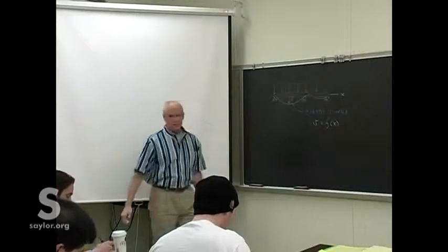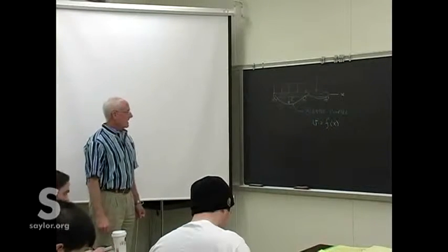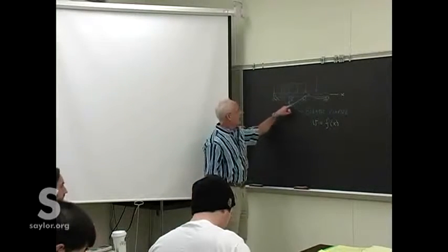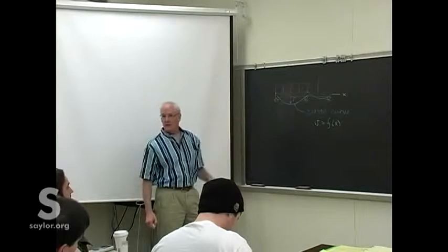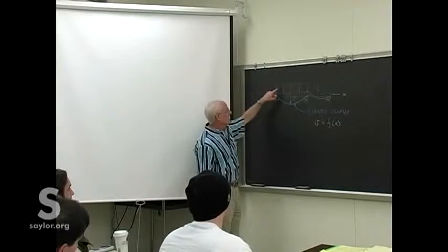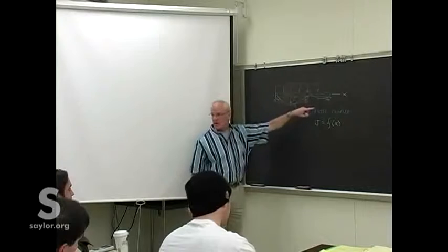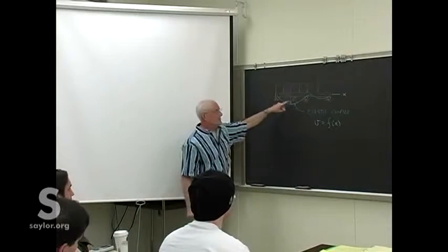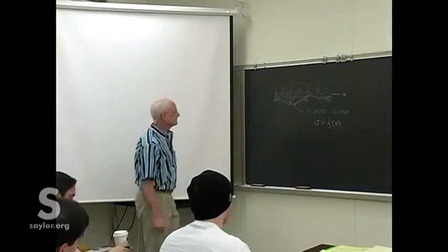So, as usual, x is down the length of the beam. We want to find out precisely what the mathematical curve is that will give us the shape of the beam once loaded. Of course it's going to depend upon the loading, and upon the constraints: where it's supported, how it's supported. The pin supports are very different from the cantilever-type supports that we see.